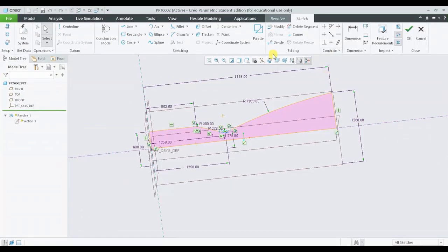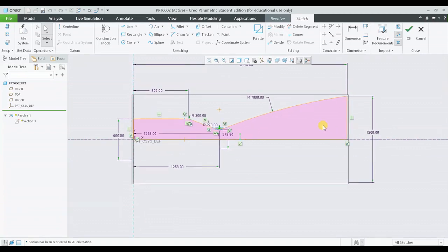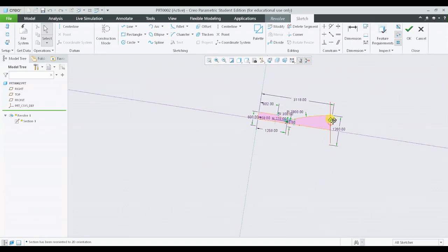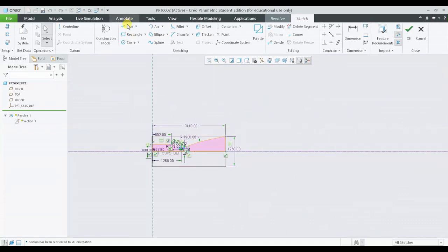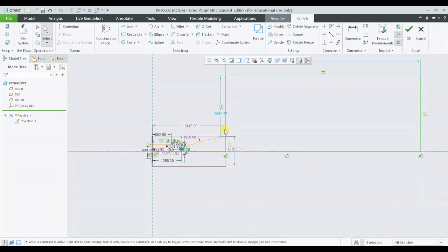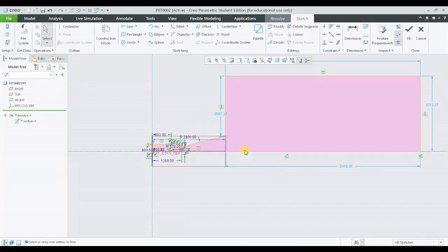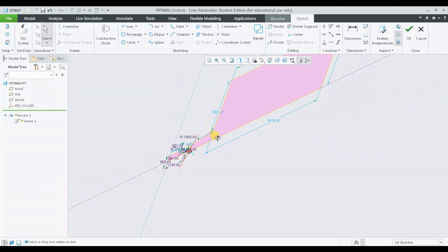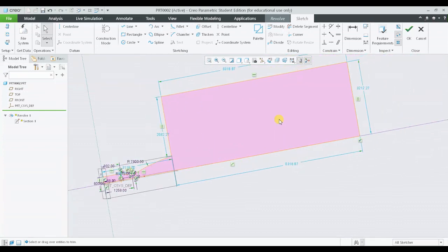For creating this particular geometry, I'll just show you what we have done. I'll just expand. From this particular location, we have extended the domain to 20 times the diameter of the rocket exit nozzle. So this was the domain we have created, and this was required for us to capture the flow field in this particular region, that is the region after exhausting from the rocket.